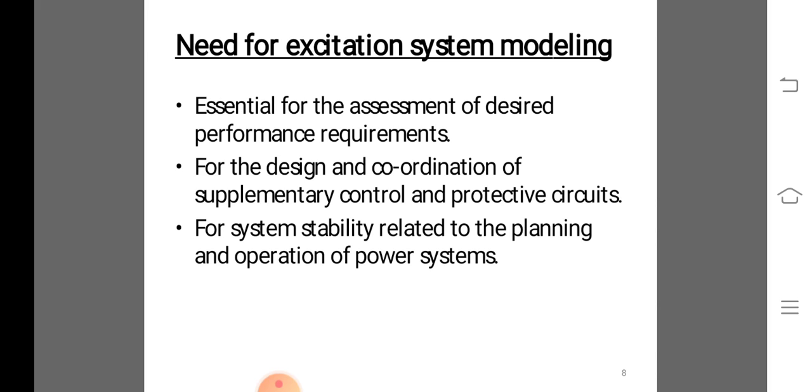It consists of a DC commutator exciter which supplies direct current to the main generator field through slip rings. The DC machine has two sets of brushes 90 electrical degrees apart, one set on its direct or D axis and the other set on its quadrature or Q axis. The control field winding is located on the D axis, with a compensating winding in series with the D axis armature current, thereby cancelling negative feedback of the armature reaction.